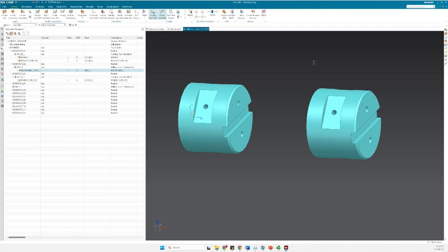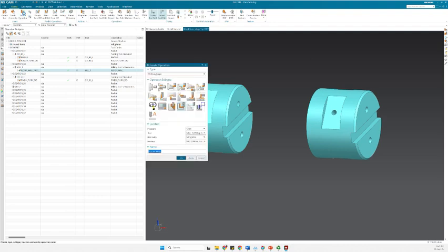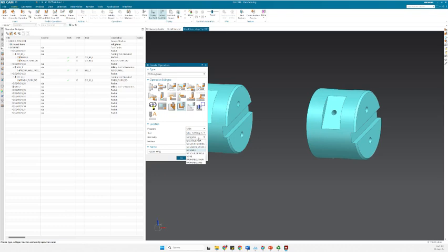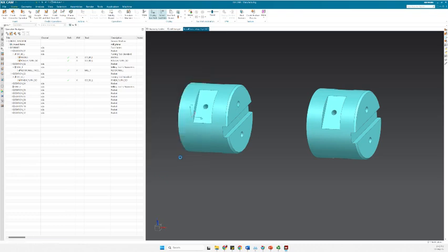All right, let's now generate the same scenarios, but now for this inclined slot. For doing that, we're going to define the same type of operations. We're going to go there, again, floor and wall, similarly to the previous one. Remember to put the machine coordinate system mill, and then also finish polar. So everything is the same, but now the difference would be the cutting area.